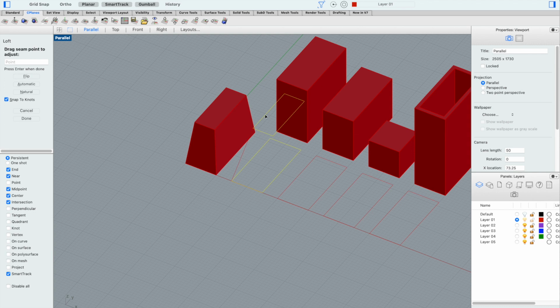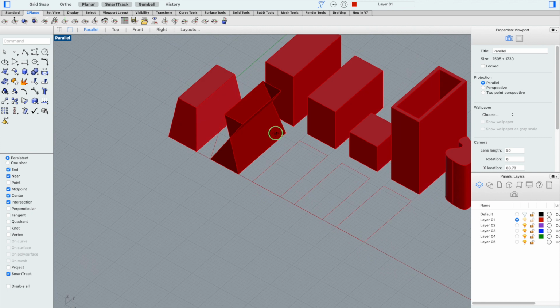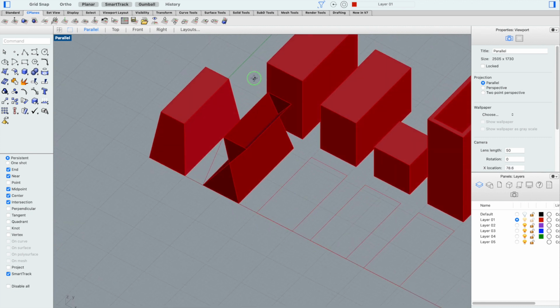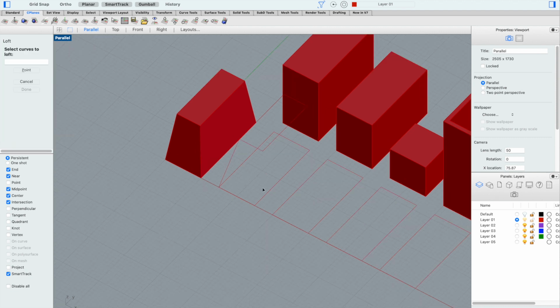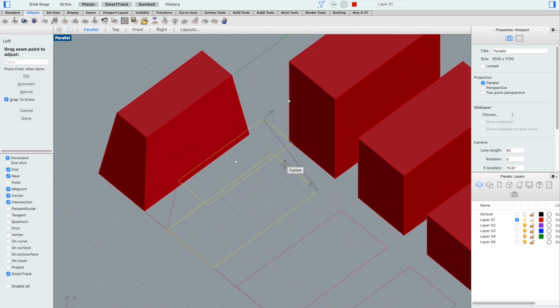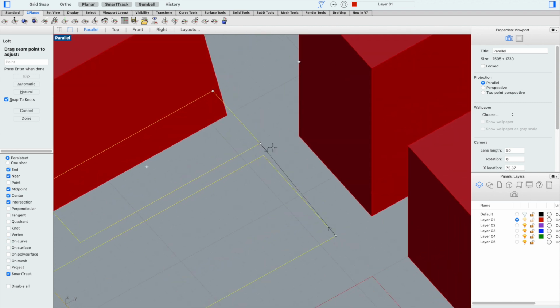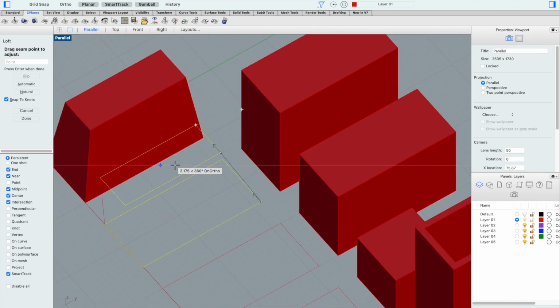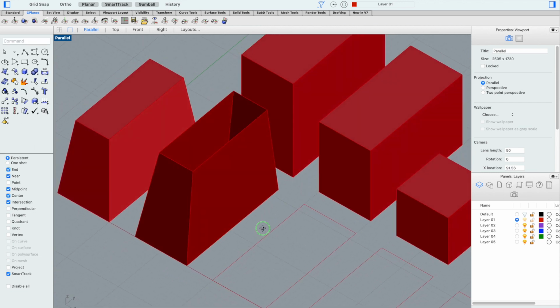This one, except it didn't. So the way that I can fix this, which is a happy accident, Control Z, loft, U, okay. And you can see what happened here is the way that it drew this curve, it kind of guessed wrong. So what I need to do is move that arrow over there. And I also need to flip it. Flip this guy. Now that those arrows are lined up into a nice tidy seam, it'll zip it up nicely.